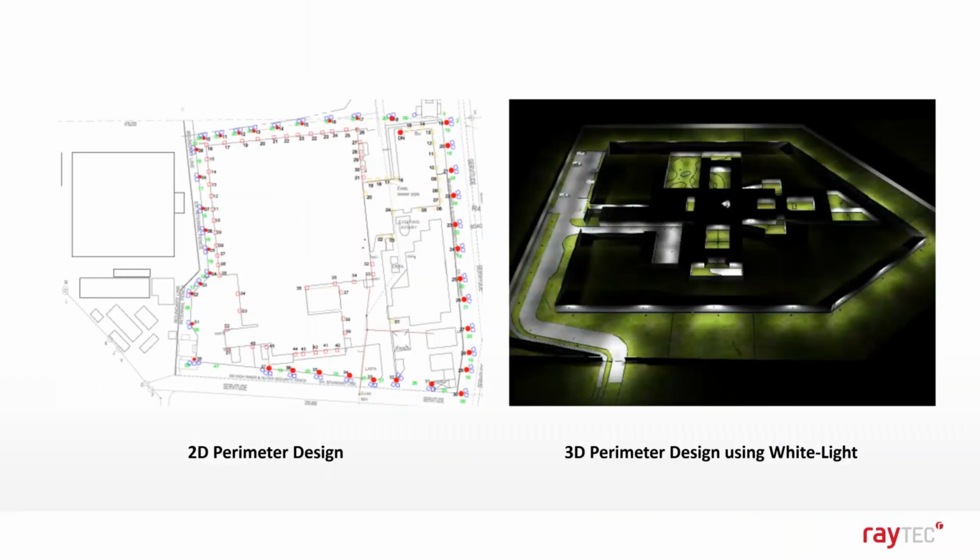So we'll take a look at the 2D and 3D here. So 2D, this one is great for plotting individual lamps and to show the direction of them. If you were to illuminate for multi-purpose, like I mentioned, on a horizontal, we could also add contour lines. So let's say that within a certain sterile zone, you want to achieve 7 lux. We could then put a contour line on the outside and inside, and that contour line would say 7 lux, and it would mean that within that sterile zone, we are guaranteeing you're going to get at least that light level.